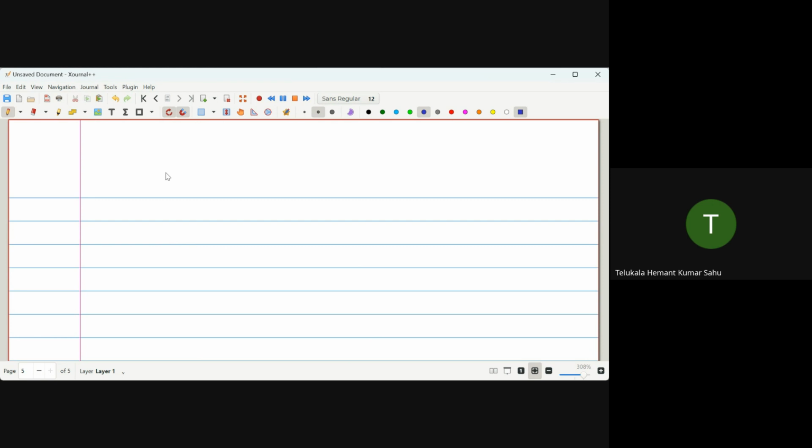In the physical calculator also, ma'am, we have learned only conversion from polar to rectangular. No, no. I told you, even going to the complex mode, in one of the sessions I have shown you, right? You have to learn it thoroughly by entering the complex mode. I mean, for the assignment purpose, I'm talking about making use of the physical scientific calculator. Not only interconversions between rectangular and polar, you can get into the complex mode. Manually, what I suggested was, if it is addition or subtraction, you better write it in rectangular form, correct? And if it is multiplication or division, you better represent it in polar. This was what I have discussed.